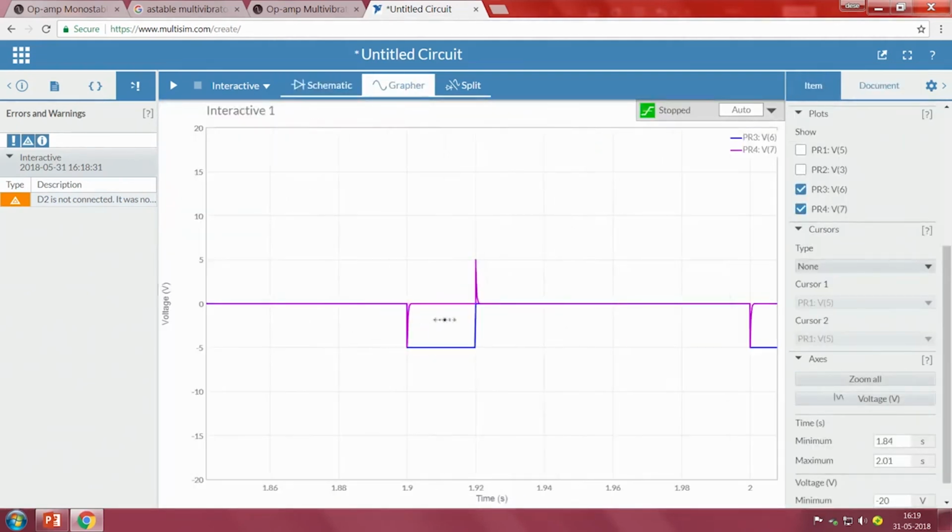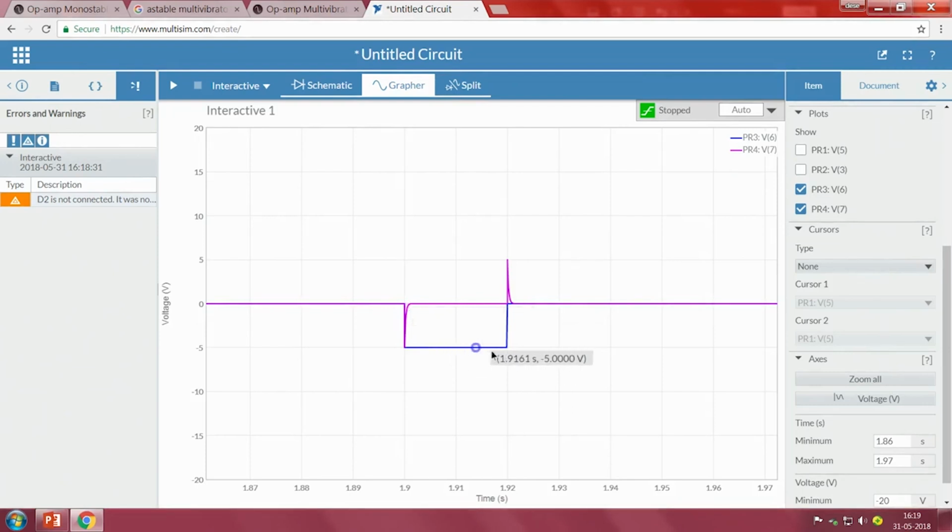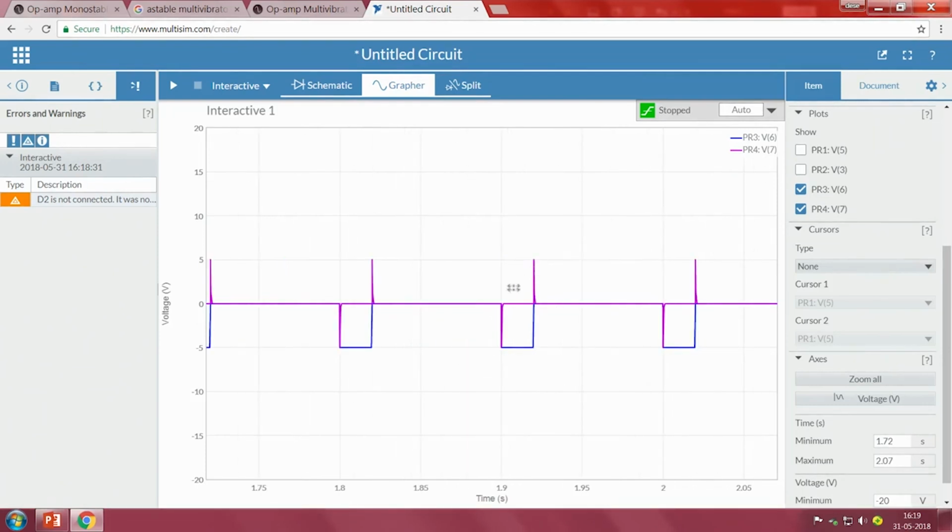Whenever we have a negative pulse, because of the negative pulse we are getting a spike, and again when there is a change from negative to ground, we are getting a spike. But if I get this spike, there will be a problem again. It allows the op amp to go to plus VCC state, but that should not happen.